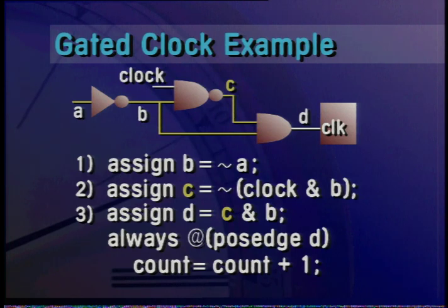If statement 3 were evaluated before the propagation of C from statement 2, then statement 3 would have to be evaluated twice. If statement 2 were evaluated before statement 3, then statement 3 would only need to be evaluated once. Notice that one way there are 2 changes on D, and the other way there is no change, triggering the counter in one case and not in the other.